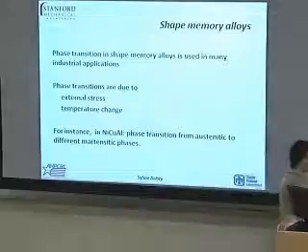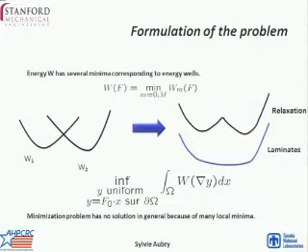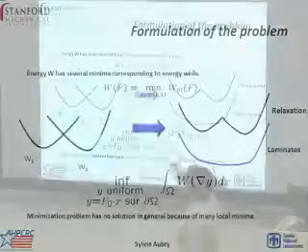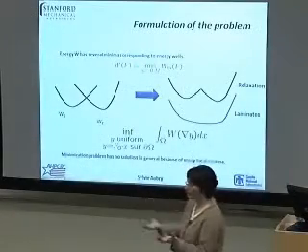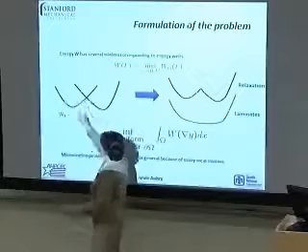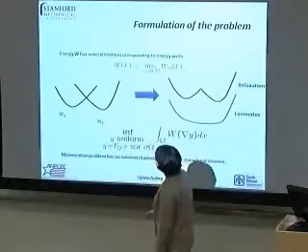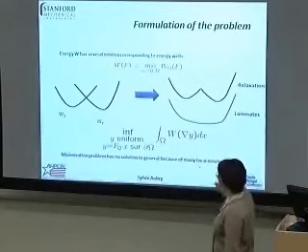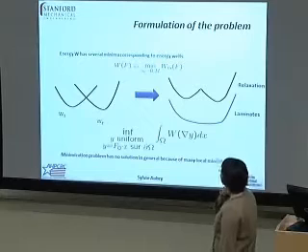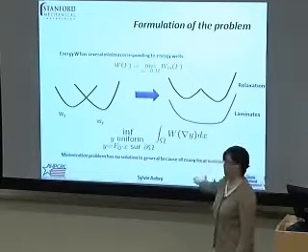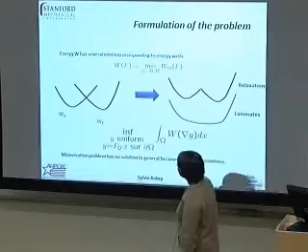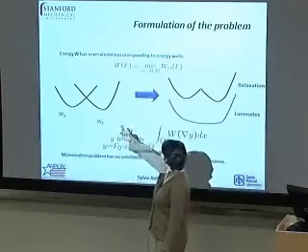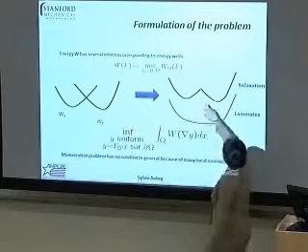Okay? So if you model the problem now mathematically, you have an energy that you want to minimize. Each variant in your martensitic phase is a convex function, here in 2D it will be like that, some kind of function. So in 3D it is an energy well. And you have several of them, you have m of them. So for example, nickel, copper, aluminum, you have 6 of them. And you want to minimize the energy of your system again. And the minimization of that kind of energy will be given by that.